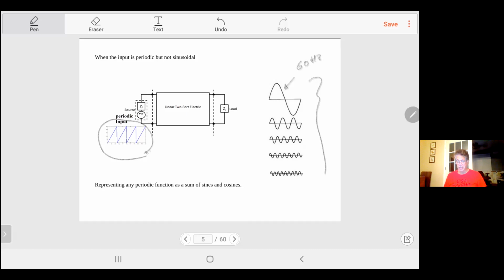What does harmonics mean? If you look at this second one, during the same period of time that the fundamental component is there, you'll find you have one cycle, two cycles, three cycles. So the frequency is 3 times. That will be the third component, the third harmonic, because its frequency is 3 times the frequency of the fundamental. And then when you count further, maybe you find the fifth, the seventh. So the harmonics have frequencies that are multiples of the fundamental component.